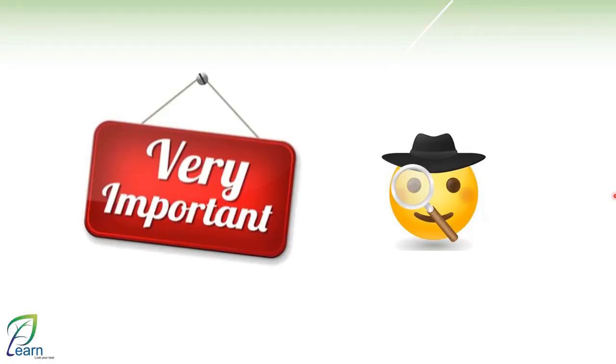In the last lecture, we talked about the Dyn5 transformer, and we saw together how when a single phase external fault occurs on the red phase on the star side, it draws currents in the yellow and blue phases on the delta side. However, we understand that the current drawn in the red phase on the star side, or passing through a coil in the red phase on the star side, will pass through a coil in the red phase on the delta side, Dyn5.